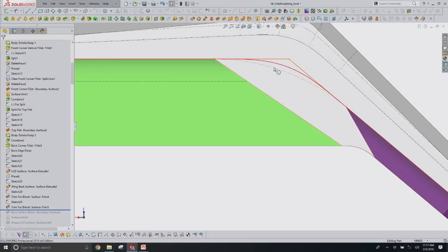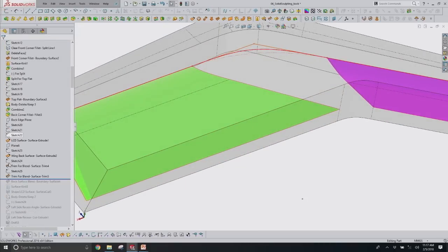So I had to play with this a little bit. I set up the size of this, and ultimately I adjusted it a couple times, which changed the angles here, because all I'm doing is connecting the end point of this fillet with the end point of this spline. Likewise over here. So the bigger this is, the more this angle changes. Also where this point is affects where this spline is, and I found that I had to kind of dial it in, get the right size, because otherwise the surface might look a little pinched.